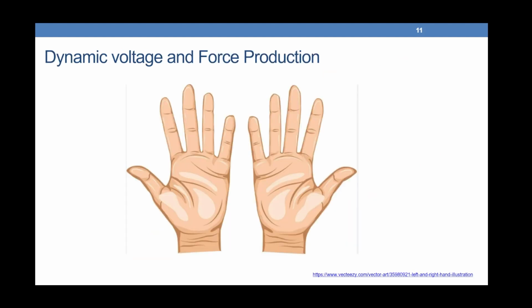So let's look at this figure. We have our right hand, our left hand. If we apply the flux to our palm here, that one is the flux density B. So for the right hand, if we succeed to push or pull the conductor by velocity V meter per second, the direction of the fingers will be negative positive E, as we can see here.